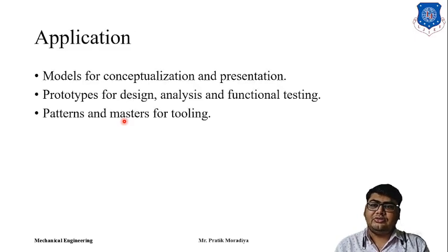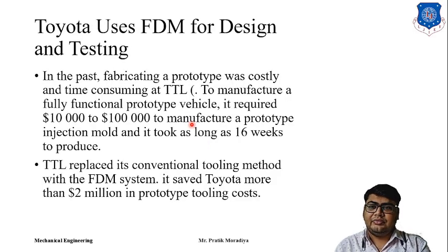Now where can we use FDM? So mostly FDM is used for conceptualization and presentation only. Sometimes it is used for design analysis and functional testing, and people have used FDM for patterns and masters. The masters are basically molds for different toolings. So this is where we can use the FDM process.